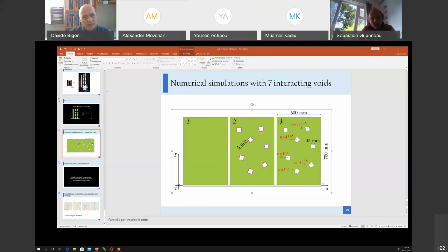Well, it depends. The way I'm using the pre-stress is in a linear way. The material is pre-stretched or pre-stressed in a way that it remains homogeneous, and so the differential equations have constant coefficients. And then the perturbation which is applied is completely general. This perturbation changes everything, but it's only an increment. So it's the linearized response of a nonlinear curve. So it's the tangent to this nonlinear curve.